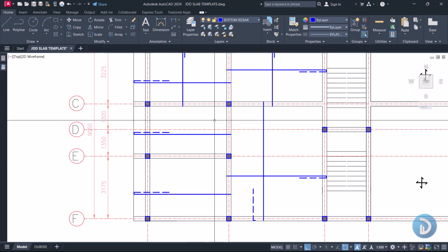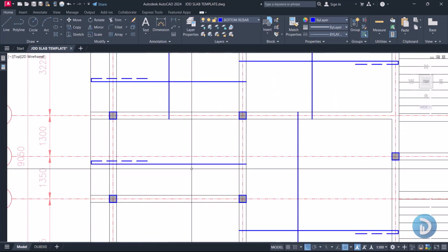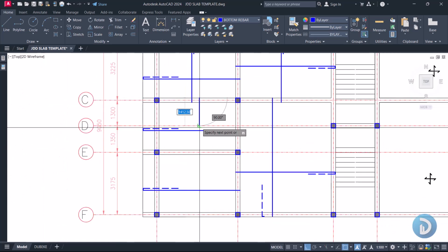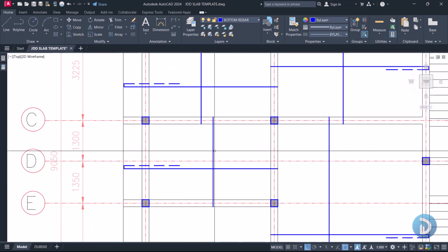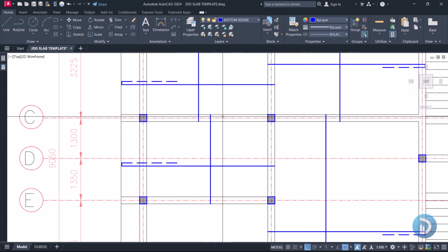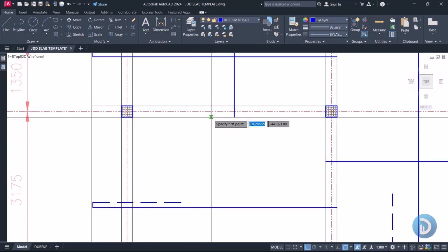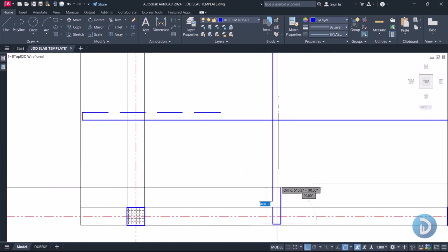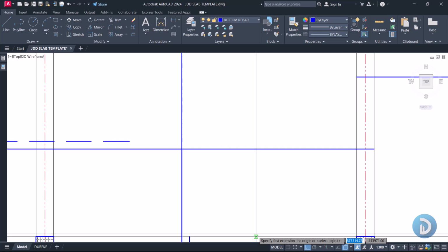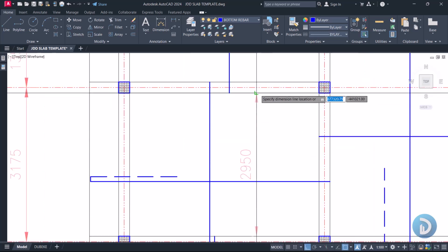Okay, then now let's come back to this vertical reinforcement. Remember, we are detailing per panels, and this rule applies to detailing per panels. So we'll come back here and we'll start our reinforcement at the end of this beam. So this, we have a slab at both the walls, top and at the bottom, so we do not need any calculations. This can stop at the end of our beams. And the next is from here to somewhere here. Okay, you can offset your 25 millimeter, then we'll return this by 100 bent up length to this part, and we can dimension this and compare it to our 600 millimeters.